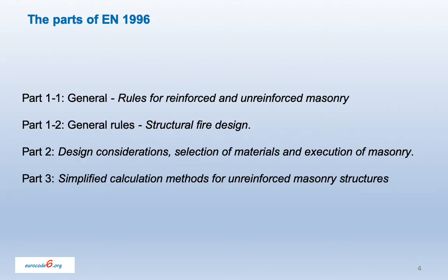Part 1.1 covers the rules for reinforced and unreinforced masonry. Part 1.2 deals with structural fire design. Part 2 includes design considerations, selection of materials and execution of masonry. And Part 3 deals with simplified calculation methods for unreinforced masonry structures. Each of these parts has a corresponding UK national annex, which is published separately.